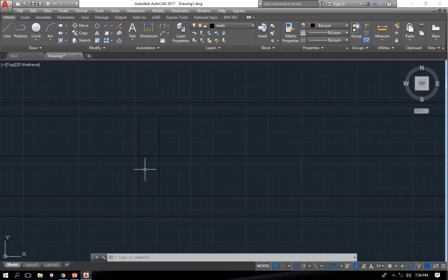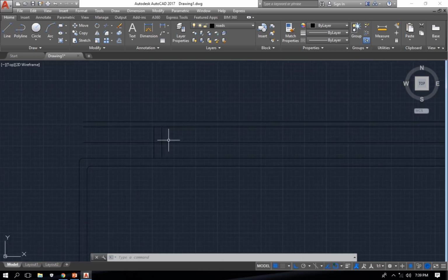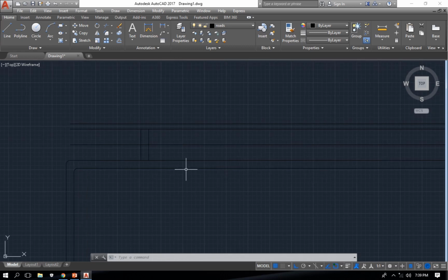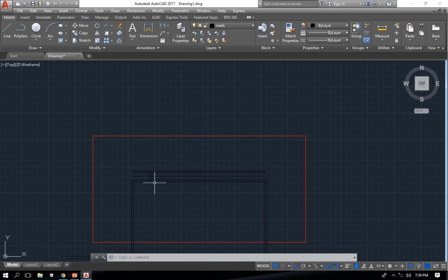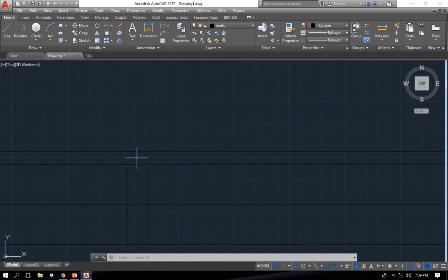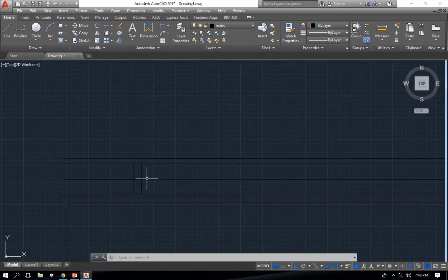Now notice that this plot of land receives its access from this road here, while the other receives it from this. You understand? That is a typical real life scenario, and which is what subdivision is basically all about. Every plot of land within the residential layout must have an access or a road giving it access. That is the whole idea.